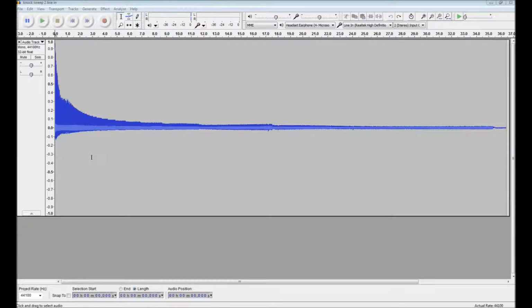This was done because I wanted to see if there is a certain amount of windowing going on after an ignition event, or if the ECU is sampling the knock data at regular intervals instead of dynamic, so to speak. So this is the signal and how it sounds if I play it back in Audacity.